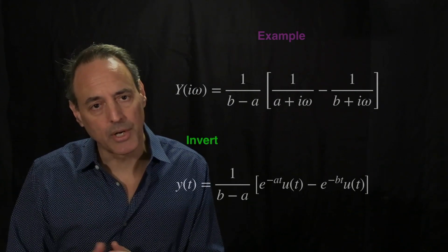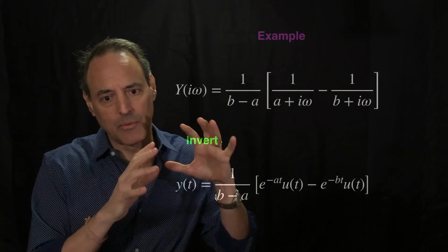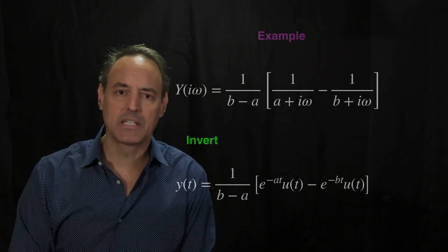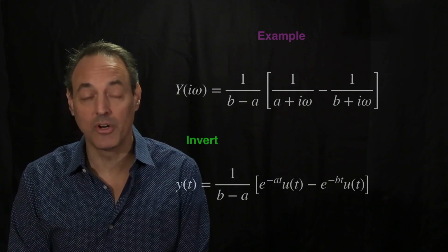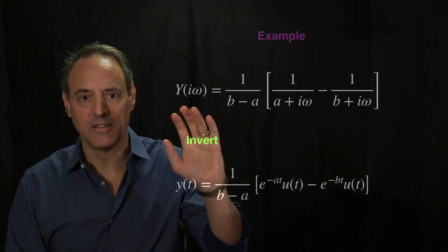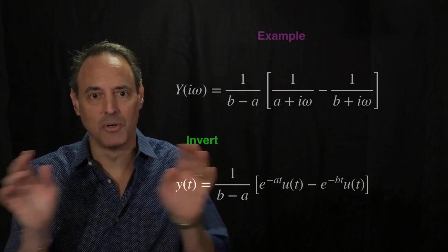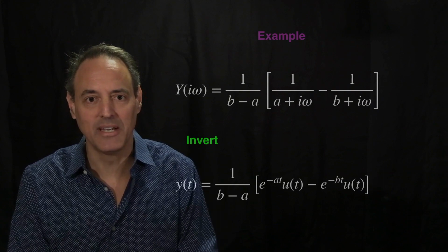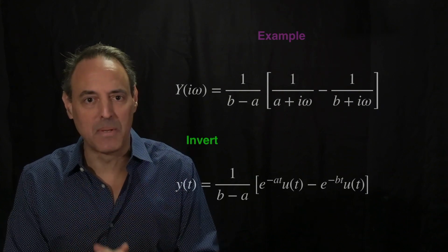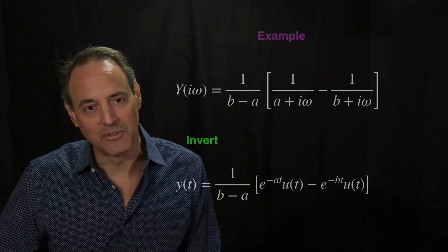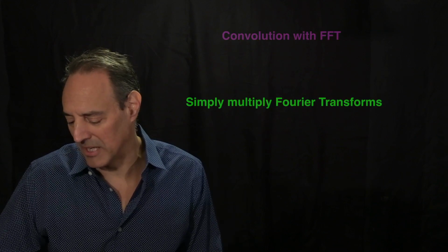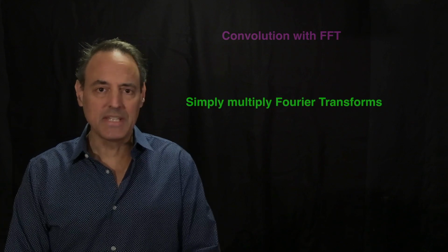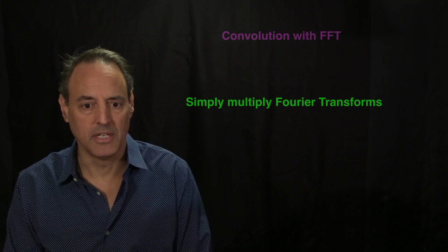So of course here we're working it out by hand, right? If you look at what we got here in these formulas, this is working it out by hand. But in practice, you would say, oh, this is trivial to do. FFT the x, FFT the h, multiply them, IFFT. Three very simple pieces of code is what you would be doing in practice in a real signal processing application.